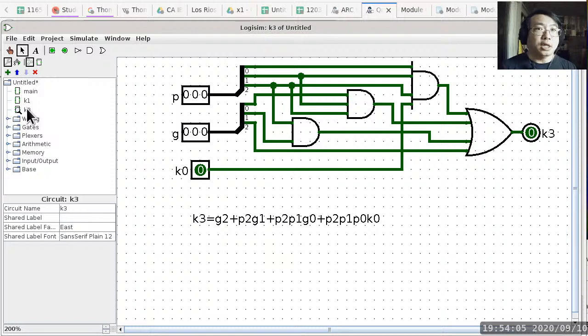And in that case, it's going to be big O of 1 because it's constant time. The amount of time it takes to finish the addition using the carry look ahead mechanism is constant time. It doesn't matter how many bits we're adding, it still takes the same amount of time. On the other hand, if you're looking at the number of gates that we need to use, I think in this case it would be to the square of the number of bits that we're adding. So it would be big O of n squared when you want to consider the number of gates that we are using.